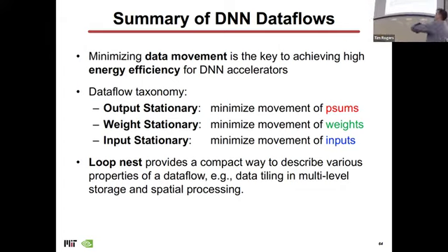We want to keep it in the smallest storage structure we possibly can. And then if you take a look at the last decade and a half-ish of accelerators that have used dataflow, because dataflow can be more efficient because there's no big register file, you can classify them into three different types: output stationary, weight stationary, and input stationary. Each of them has trade-offs on which one you'd want to use. So there's no one size fits all. And I've given you some concrete examples.